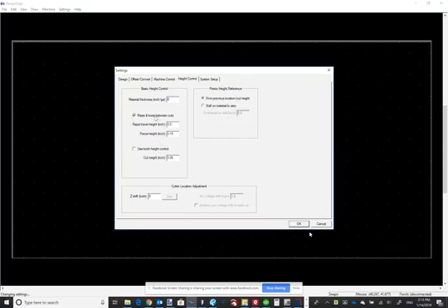So with basic height control, I explained all these settings elsewhere, but if you've got stuff that's grayed out that you can't change, it's probably because you don't have options enabled. If you don't have it set to raise and lower between the cuts, then it doesn't need any reference. If you don't have the use torch height control checked, it's not using the arc voltage. So when you check that, those things will come into play. Let's see, let's look back at that.